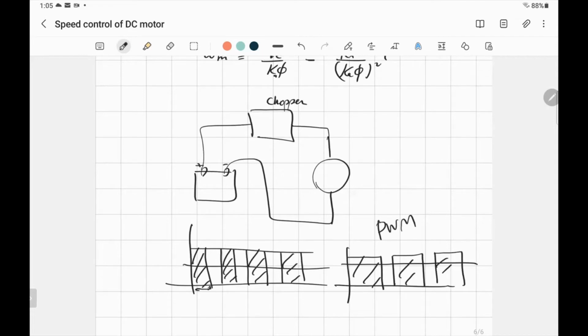And the advantage of this one over the resistor that you insert in the armature is that the other one has power loss, copper loss, I square R. But that's the method used before. They still, of course, use it till now, but with small models. They are not going to bring a chopper and pay the cost. And originally, the current is very small, doesn't exceed 1 amp, for example. But if you talk about a big DC machine in factories or anything, it takes about 20 amp. So they use power electronics.